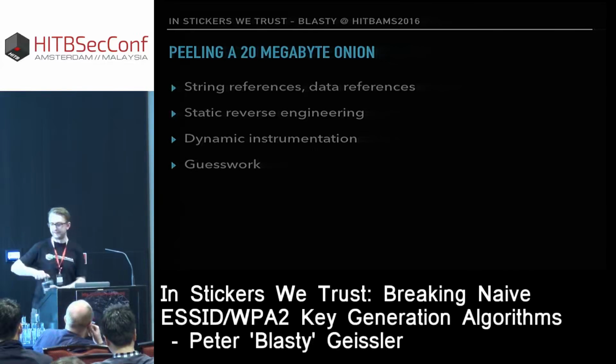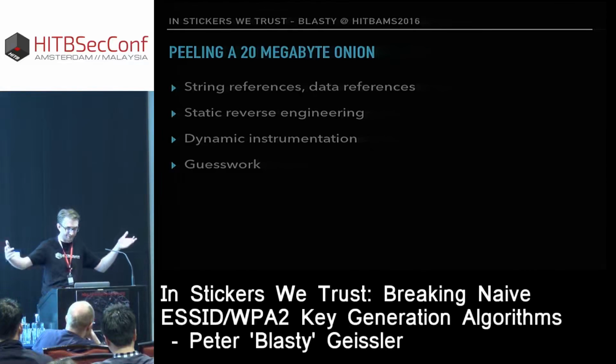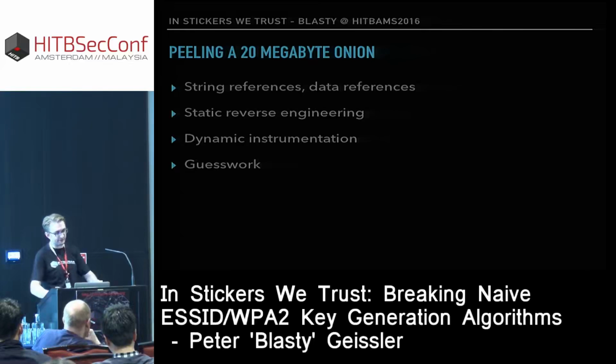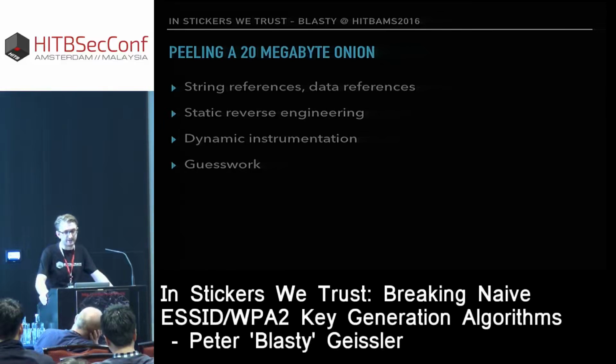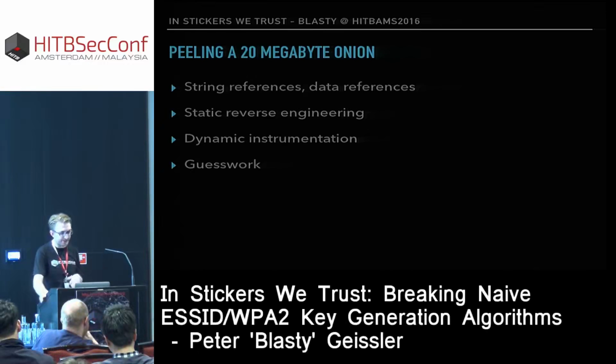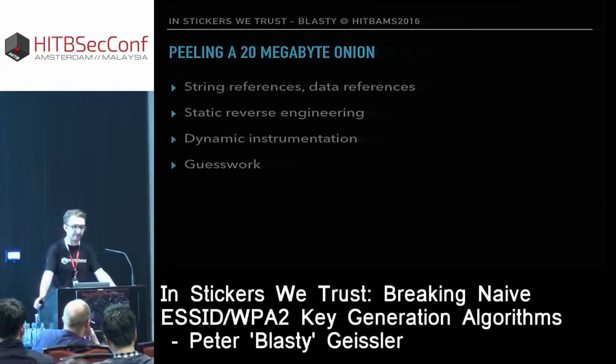You cannot say, I want to reverse this firmware. The firmware is a 24 megabyte thing. How can you ever reverse all of that? So you need to have some specific goal in mind. For example, when I was looking for the NAND flash routines, we have string references to go by. It starts with NAND flash read, so we can use that as a point for identifying things. So using static reverse engineering, you can find some things.